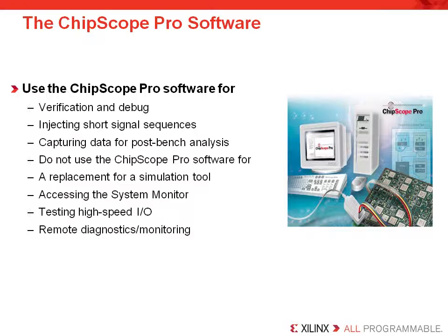The ChipScope Pro software was originally designed to solve the problem of looking inside an operational FPGA without having to bring collections of signals to I/O, which impacts performance, routing, and requires an external header for connecting to a logic analyzer or scope. Over the years, it has gained in versatility and power and can now be used to inject signals into the FPGA using the VIO core.